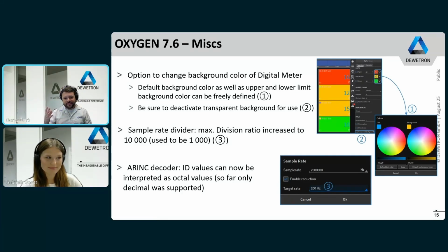One of the other really nice software hardware features we've had is the ability to divide our sample rates. We do it a little different. When we do sample rate division, we don't just throw away samples. We actually set up the filter properly for the channel, set up the ADC for the new sample rate on that channel to give you really good recording.